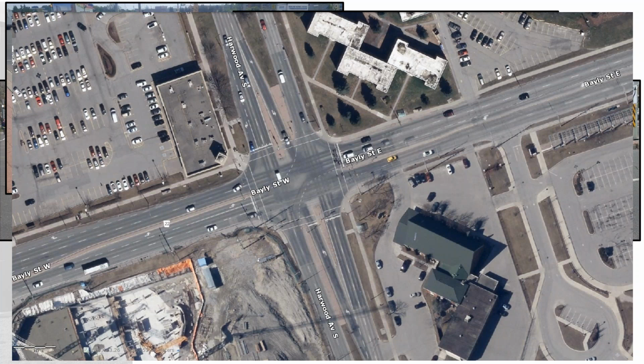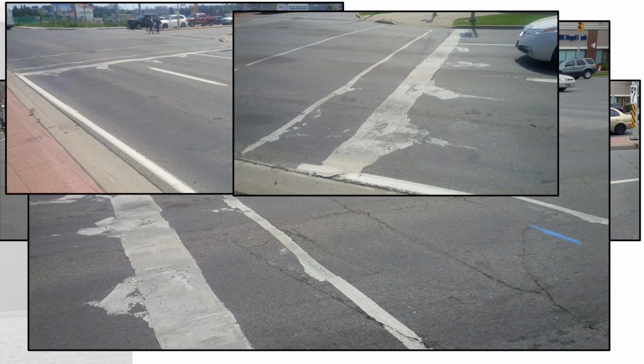So we put forth the idea of a rigid pavement pilot project to address the rutting, and we selected this intersection in Ajax, Harwood Avenue and Bailey Street. This was in 2015, 2016 that we were talking about this. The intersection was last reconstructed in 1999 when these slotted left turn lanes, you can see, were built. So that pavement design in 1999 consisted of 40 millimeters of HL1 asphalt, over 100 millimeters of HL8, over 150 millimeters of new granular A base, and 600 millimeters of granular B subbase. And there was early rutting and shoving identified within 1 to 2 years. So by 2001, those pictures that I showed you back here, that was pretty much what it looked like within a couple of years after construction.